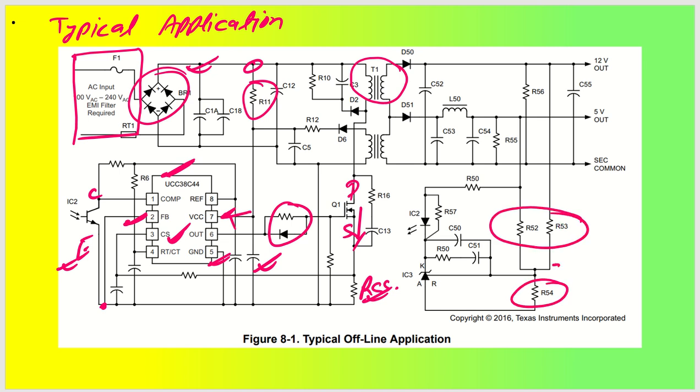They are going to decide your feedback pin voltage level, and at the same time we have a reference IC, okay. So this is a kind of shunt type reference, or a reference voltage, let us say TL431 you can utilize for this particular purpose. So TL431 is generally used for this reference voltage setting, and this output is going to get into the primary, towards the feedback side of this particular IC through the optocoupler, okay.